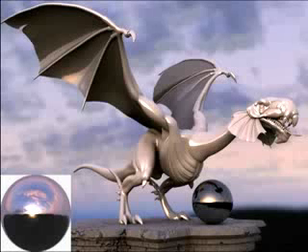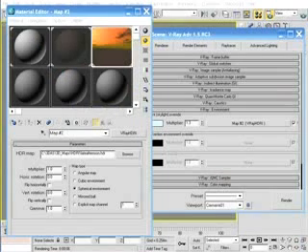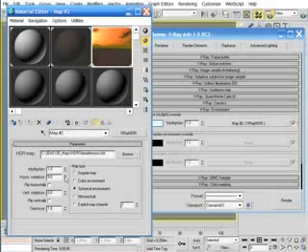in color. But you're not limited to the default orientation, and one of the great things about the HDRI map is the ability that you're given to rotate the map to achieve a particular look to the lighting. So you can rotate the HDRI around your scene using the horizontal and vertical rotation parameters here.